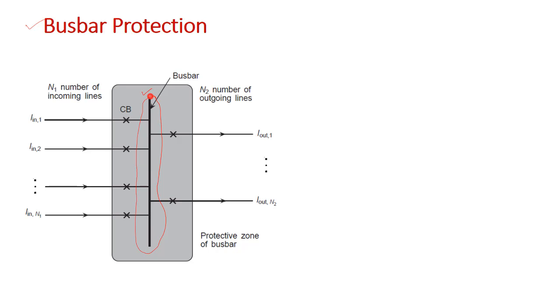If you have visited any substation, you might have seen the busbar arrangement where the incoming and outgoing feeders are connected. The incoming feeder gives the power supply, and through the outgoing feeder we take the supply. In between we have various connections with the transformer, etc.